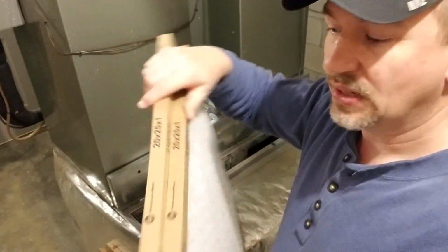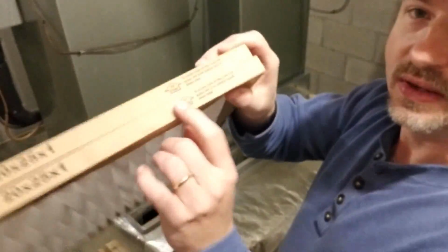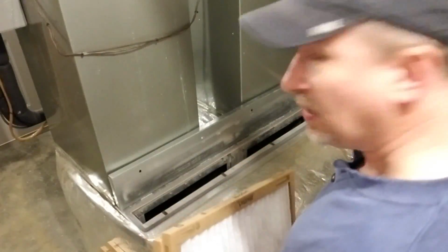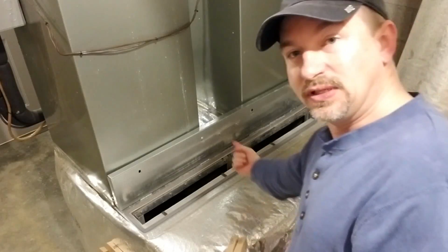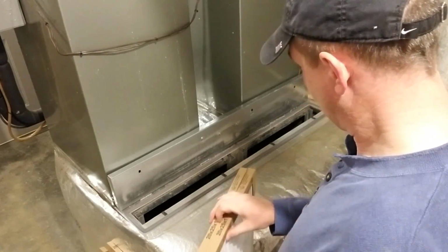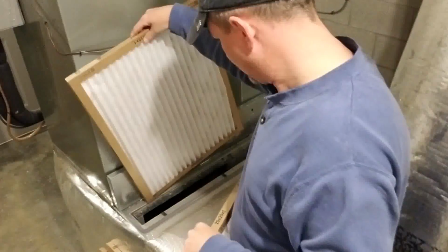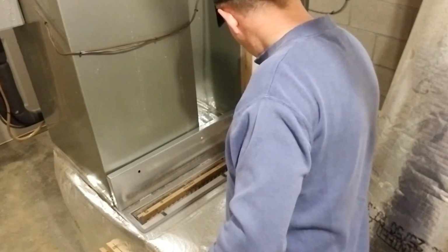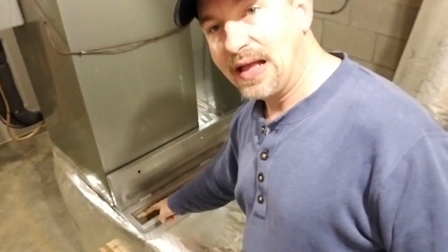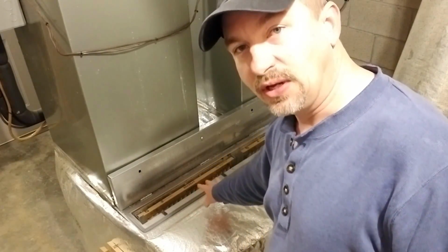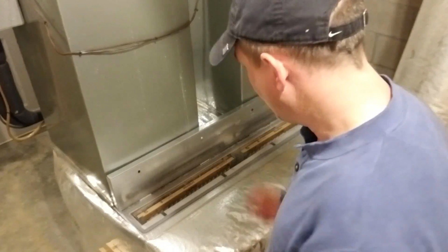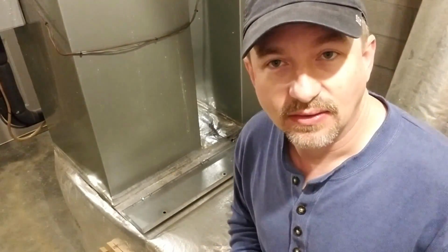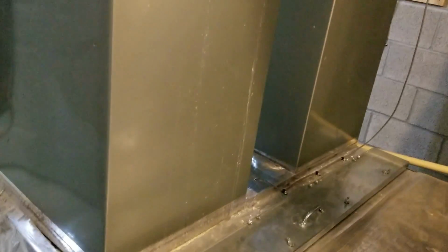And we'll put our new ones in. Always checking the little arrow here to make sure the air flows in the right direction. And in this case, air comes down the big pipe and goes in this way. So there's guides in there so that those can go in nicely and everything. And then close this little thing and put the bolts back in, and that's it. So it's pretty easy to change the air filters.